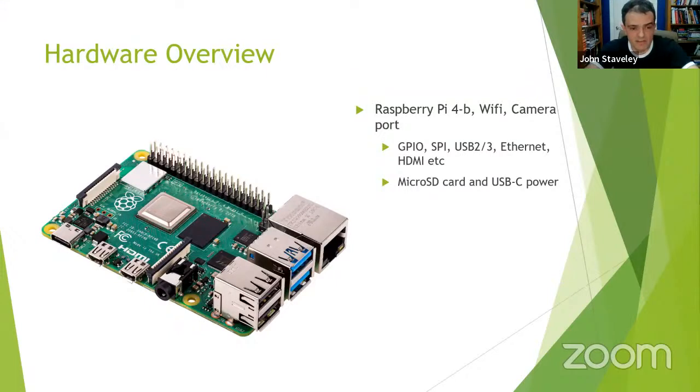So this is a Raspberry Pi. This is the version 4 of the board. Going around, you've got an Ethernet port here, a couple of USB 3 ports, USB 2 ports, an audio controller. This is the display, the camera ribbon port, 2 micro HDMI ports, a USB-C port, a display port. Hidden under here, you can't see, there's a micro SD card, and that's what the operating system sits on. This is your Wi-Fi chip, and this is your CPU.